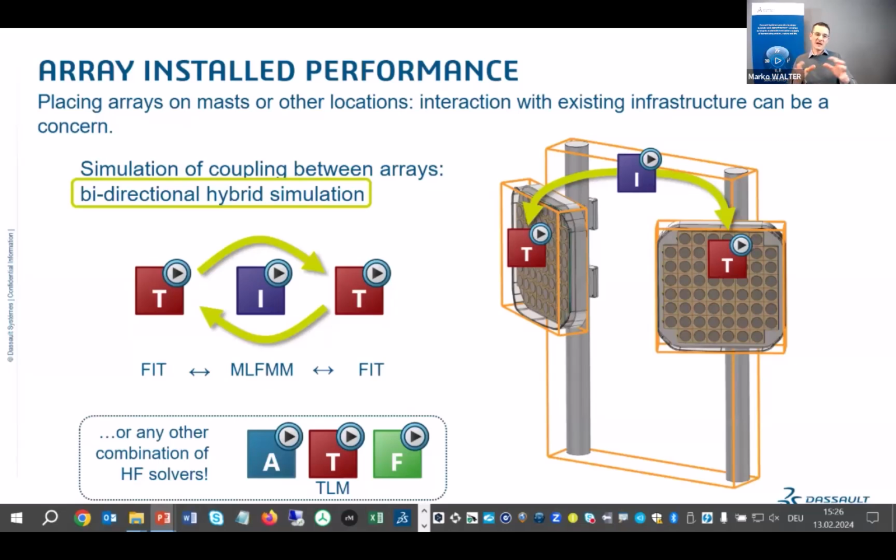But we use a time domain approach, and the space between them, so the coupling between them, we are simulating using an integral equation approach. So that's kind of simulating this relatively small channel, so the local environment. And the hybrid solver provides this kind of unique combination of time and integral domain, or as we'll see, any other combination of high frequency solvers, which allows us to really accurately study the coupling between even quite complex antennas. There's a link, so we'll post this afterwards, to a talk specifically about this topic on our website.